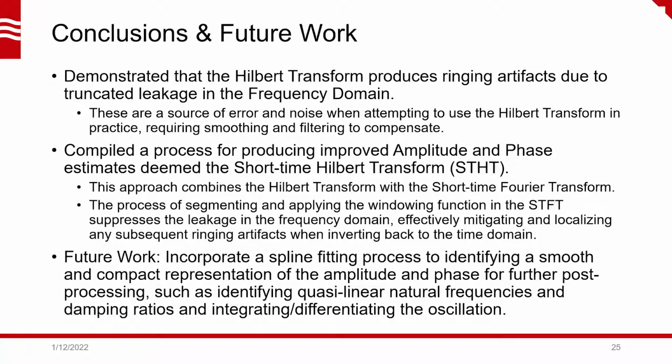For future work on this, I'm working on a process of fitting an optimized spline curve directly to the amplitude and phase to get a compact and smooth representation of each, with which you can do more post-processing, like identifying quasi-linear natural frequencies and damping ratios, and integrating or differentiating the fit oscillation.